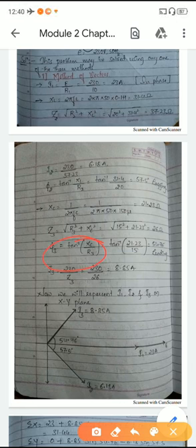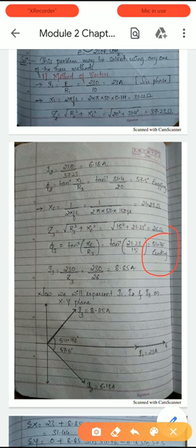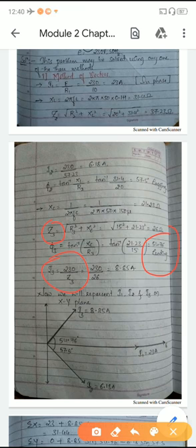Again it is a circuit consisting of a capacitor, therefore the current will always be leading by an angle of phi with respect to voltage. Hence here the current is leading by 54.76, and we know the value of Z3. We can calculate I3 also. I3 is 230 divided by Z3, so we are going to get 8.85 amperes.